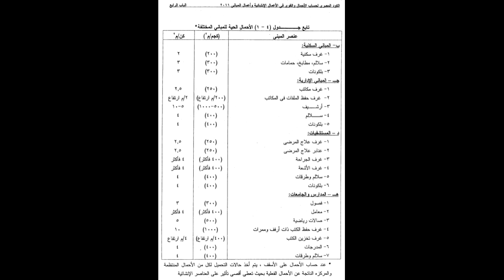We'll go now to the hospitals. Patient rooms 250 kilogram per square meter. Curing rooms 250 kilogram per square meter. Operation room 400 kilogram per square meter or higher, depends on the equipment used in the surgery room or operation room. Also X-ray rooms 400 kilograms per square meter or more, depends on the equipment weight.